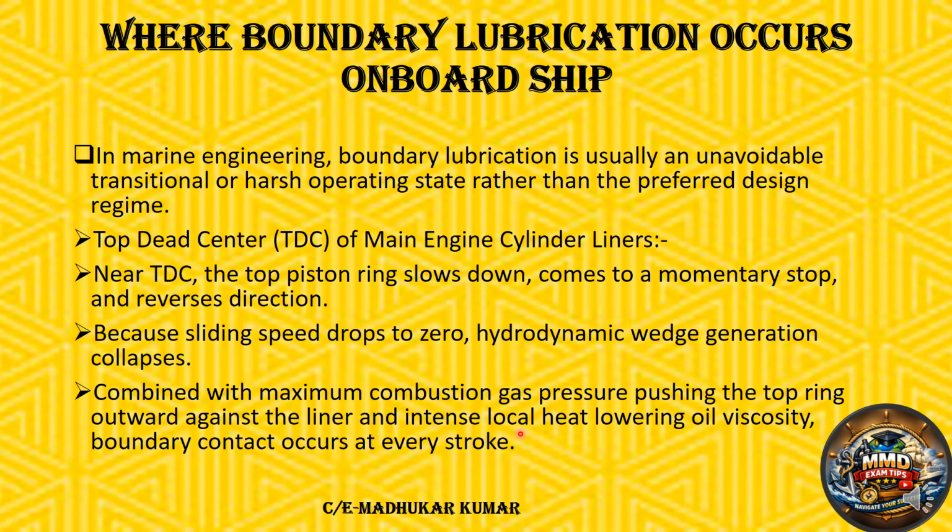So this is a very nice explanation. Basically, you have the high gas pressure on top of the piston, and not only that, we also talk about the lube oil condition: the viscosity will drop because of the high temperature. So how do we maintain sufficient oil film thickness? That's why boundary lubrication exists over there. This is very important to understand. This is a transitional phase. Okay.